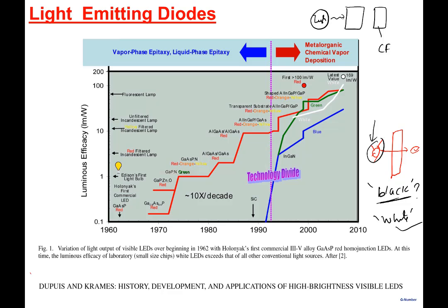And this color filter, if you have a red color filter or whatever, allows a red light or a green light or a blue light. So you're getting red, green, and blue through filters. So you can see why LCD is inefficient also, because you're passing only white light and you are allowing only red light to pass through. What happens to green and blue? You're just rejecting them. And this light source is always on.